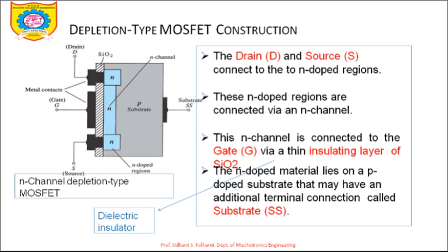Now, closely observe the MOSFET characteristics. The basic thing that you need to remember, if someone asks you what is the difference between depletion type MOSFET and enhancement type MOSFET, is that in the depletion type MOSFET, the channel is already present, and the electrons emitted by the source go through this channel and are collected at the drain side.